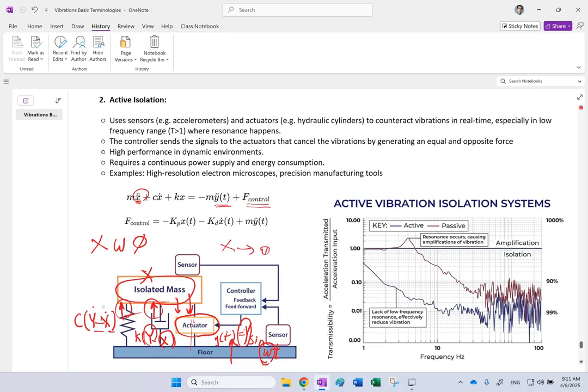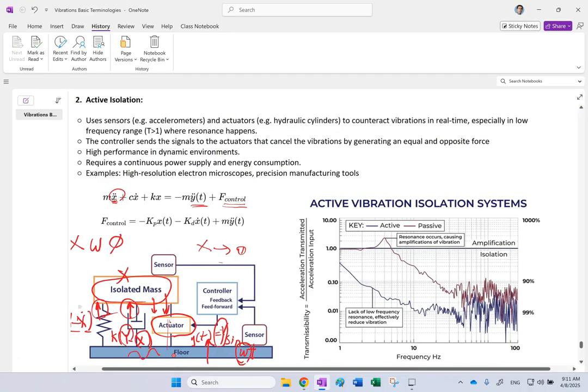Then we say we fully isolated the vibration and did not allow this x to constantly feel this harmonic excitation. Okay, so although the bump under the car is continuously oscillating, your x gets some small motion and then very fast goes down to zero, so you literally don't feel anything.